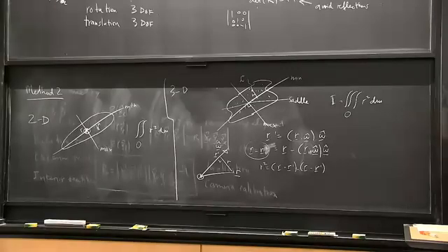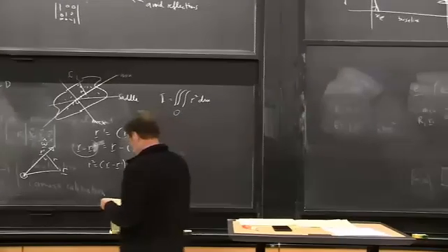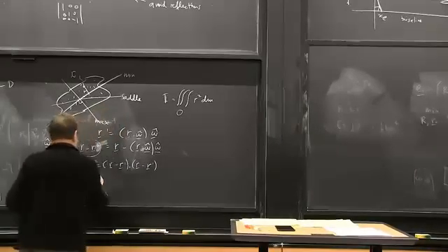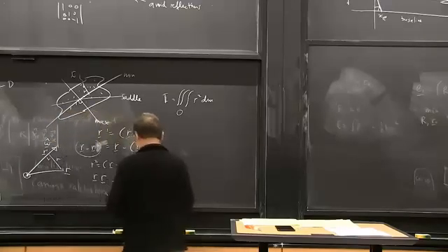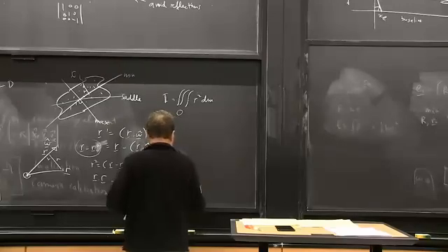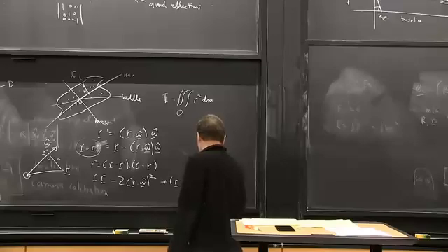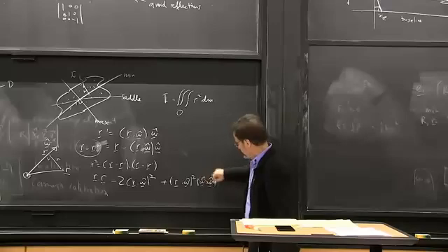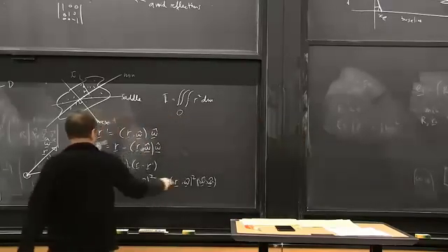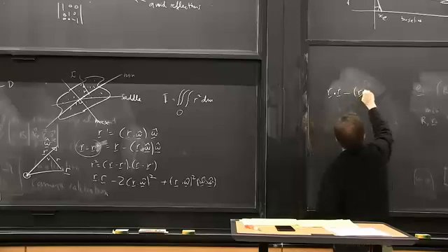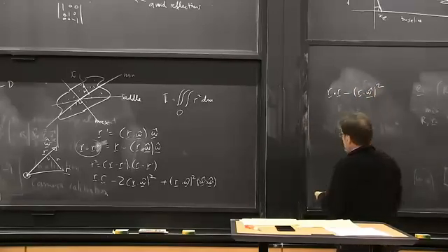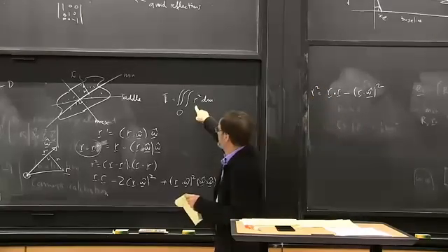Okay, and so we need r squared. Don't worry too much about this algebra because we won't be using this again, but at least try and follow it, and tell me when I screw up. If I multiply this out, I get r dot r, minus 2 (r dot omega hat) squared, plus (r dot omega hat) squared. That's because there's an omega hat dot omega hat, and this is a unit vector, so that's just a 1. Since two things have the same form, I end up with r dot r minus (r dot omega hat) squared. So that's my distance from the axis, and that's what's in the formula for inertia.